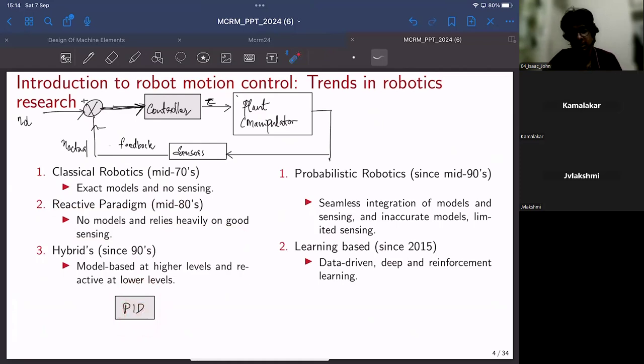It can be very fast, it can more or less predict the errors very fast. But it will be a bit difficult to correctly tune these PID gains. All in all, it's much more sluggish. The error tracking basically becomes a bit sluggish if you are relying only on pure feedback or only on sensors.